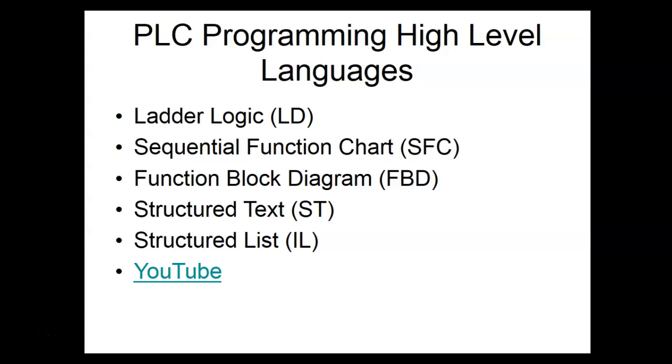But when we download it, what does it do? This PLC has no idea what a normally open contact is. It compiles it over. This program application actually says compile. What a compiler does is take the entire program and convert it to binary. You still have your main program. But if I run a simulator like that Logic Pro that I showed y'all, that runs a translator, so it never generates a true machine code program. It's translated on the fly.